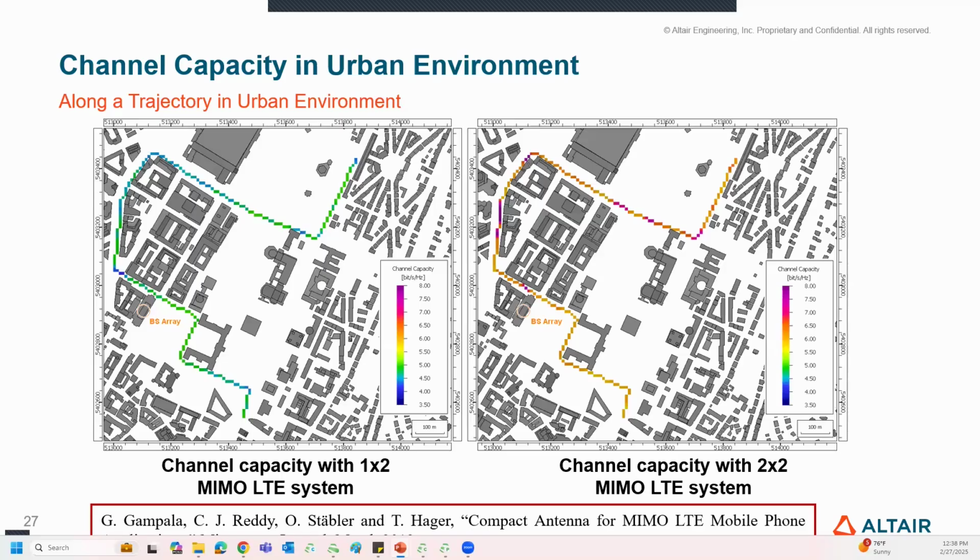You can start with the basic antenna on its own to initially come up with a base design. Once you have a base design, you can start building on top of it. In this case, we added the bigger ground plane of the mobile handset, and then we added the other parts, the LED screen as well as the battery, and checked how the antenna is performing.